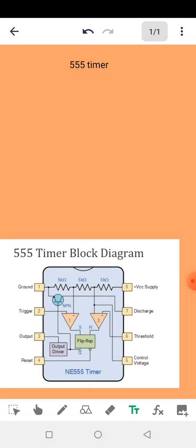I used it to design a switch to tell me that the tank's water level indicator for a tank. I've used it to design a kind of touch switch. I mean, the applications are actually limitless. You can use the 555 timer for timing. You can use it for free oscillations. You can use it for generating pulse signals. You can even use it to design an inverter.